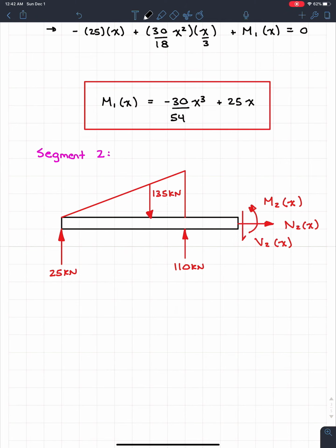So now the question becomes this. And both actually work. So there's only going to be one trick. So we know that the length of this beam is going to be one of two things. I'm just going to put tick marks here. And the first one is I just say the whole thing is X. Now, this is not how I used to do it. I'll show you how I used to do it, but this is what I recommend now. And I'll tell you why. It's because it keeps the left side of the beam at X equals 0. In our equation, the very left side of the beam will be X equals 0. And then right here will be X equals 9.